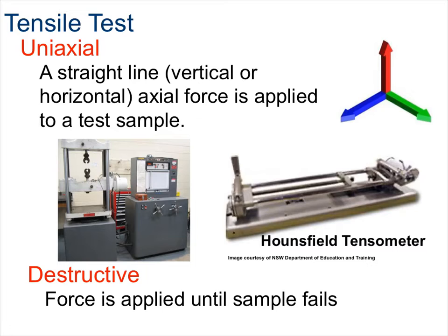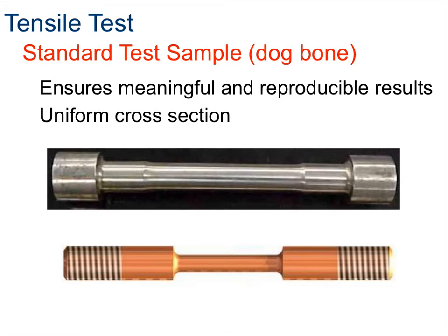But in order to conduct a tensile test, engineers often require the use of a machine called a tensometer. A tensometer device consists of two grips that hold each section of the test material in place. Tensometer instruments can create the force through the use of either a screw or a hydraulic ram, which are powered by mechanical or electrical means. The amount of stretch that a material has when it's under strain provides important information about the material's tensile strength and fatigue strength.